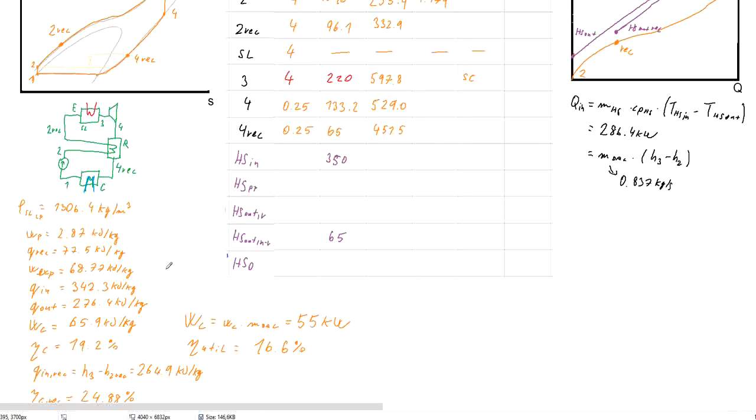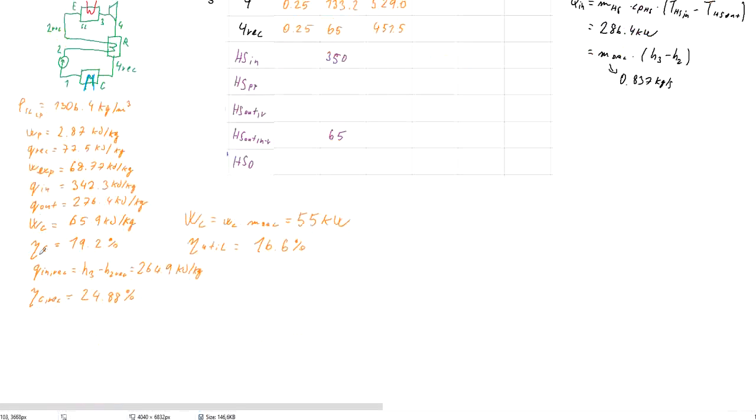And for the supercritical ORC, efficiency of the cycle based on the recuperation 19 to 25%. So you can see that if you have just cycle efficiency, it does not need to show the whole picture for the power output that you can get, especially in applications of waste heat recovery. So this was the tutorial for the organic Rankine cycle.